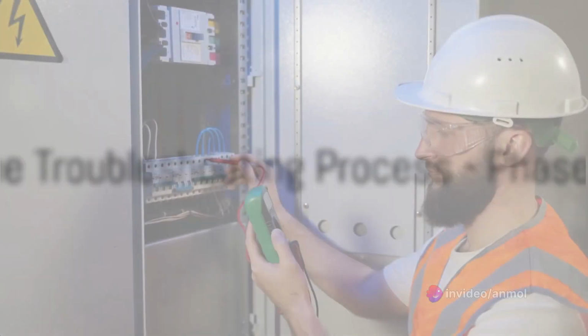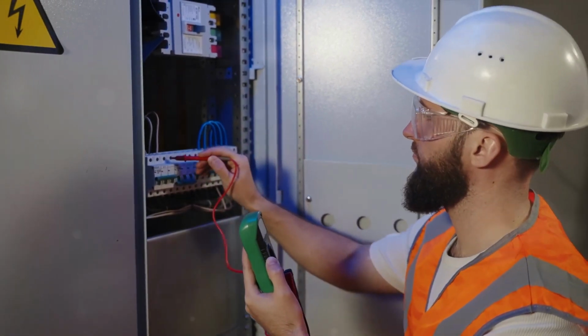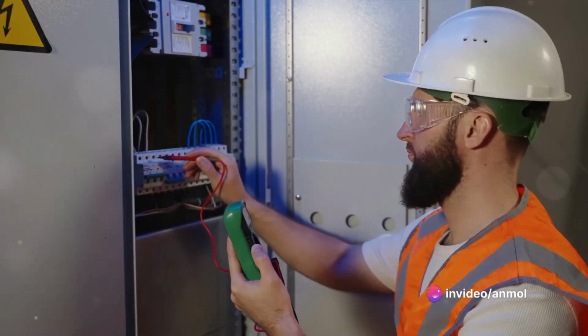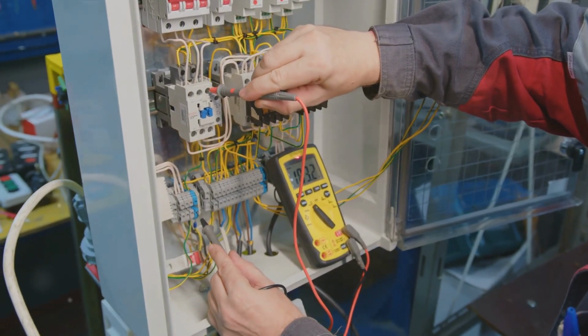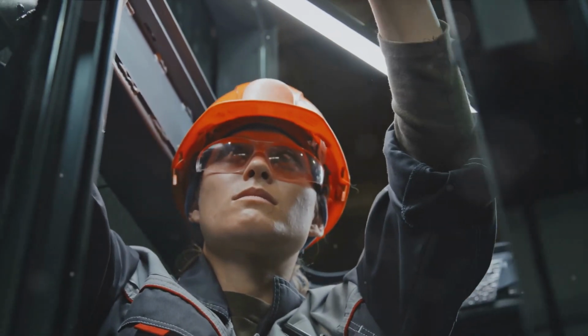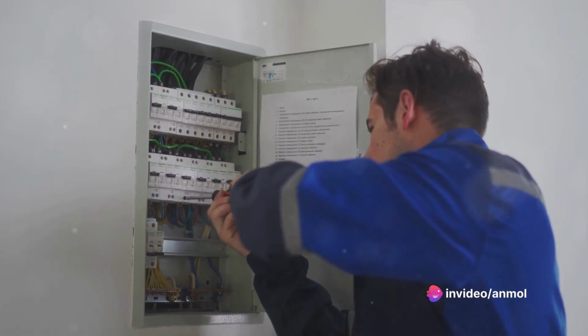Once you've made your initial observations, it's time to dive deeper with the second phase, testing. In this phase, we're going to use some tools of the trade, such as a multimeter, to probe deeper into the variable frequency drive, or VFD, checking for issues in the power supply, control signal, and motor output. The multimeter, a versatile tool, can measure voltage, current, and resistance. It's a staple in any technician's toolbox and a key player in our troubleshooting journey.